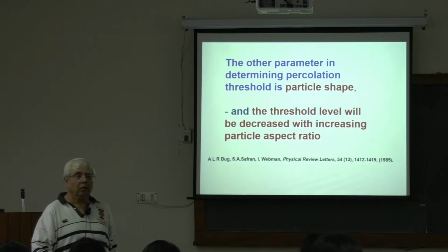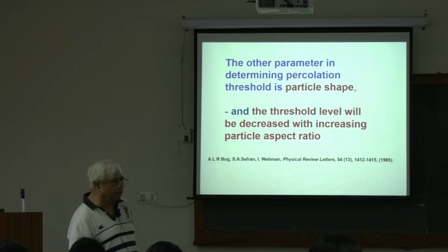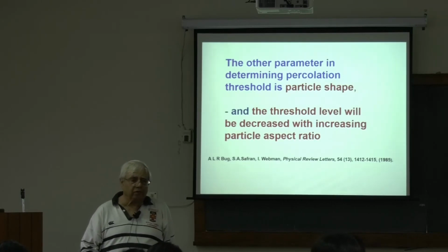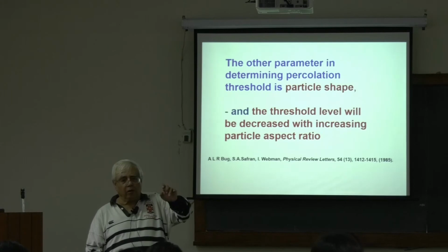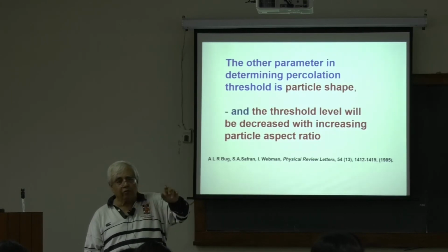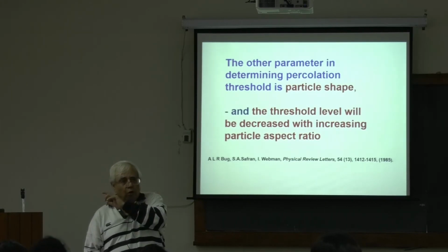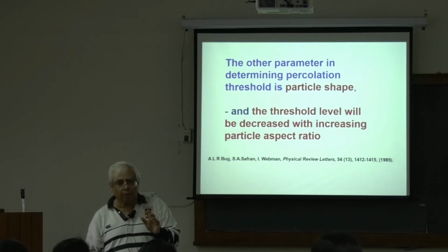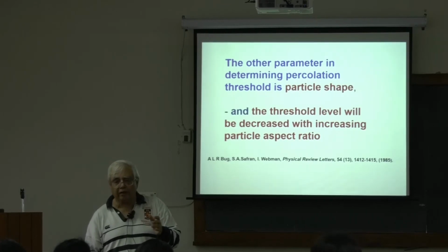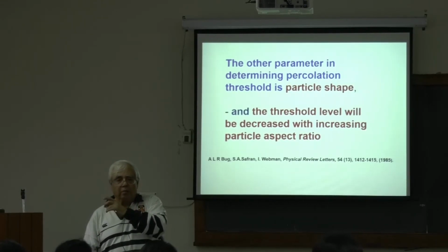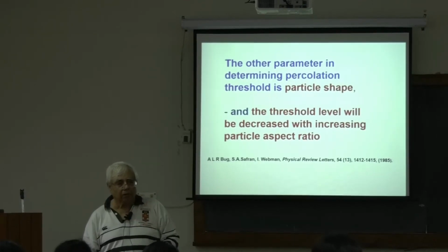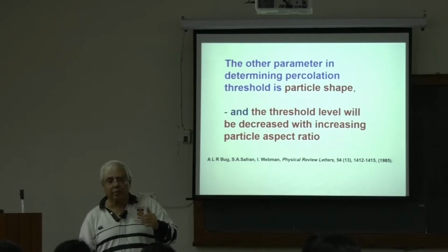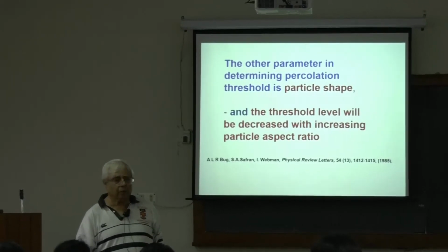That's why if you have longer things, you might ask the question, how about fiber reinforced plastics? So if you want to get a stronger one, you have continuous fiber, like carbon fiber from one end to the other end. That will give you much less problem. That's why all composites in planes and other things have long carbon fibers, maybe meters after meter. But sometimes, if we have short carbon fibers, then you don't get that much strength. All right?